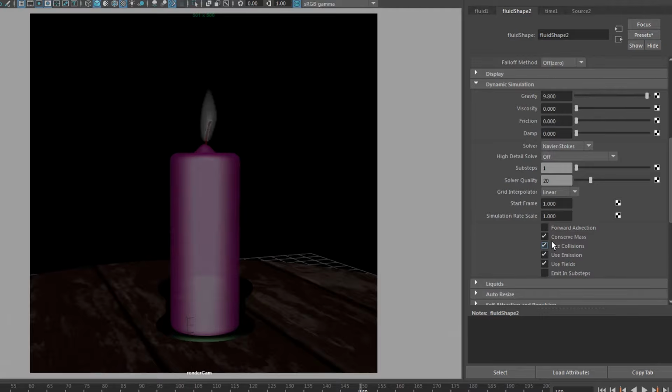And it has an impact on both density and temperature. So let's set the damp to a very low value, 0.075, which is considered an okay value, almost a medium to high value for damp, because it suppresses the flow in the container, and a very small value can make a huge difference.